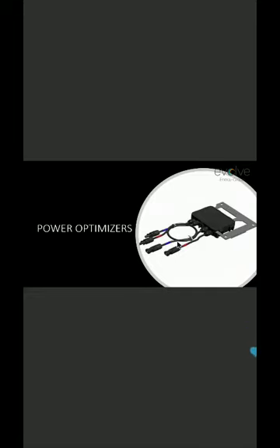Okay, we have now finally come to the topic of the power optimizer. What is a power optimizer? Why do I need a power optimizer at my site? Because we are saying diodes will engage into action and do all the things, then why do I need an optimizer? As we clearly say, an optimizer is not made for shadow. It is needed for mismatch, different orientation, soiling, different types of degradation, and safety purposes. Many advantages are in this optimizer technology. We will look at them one by one in this webinar.